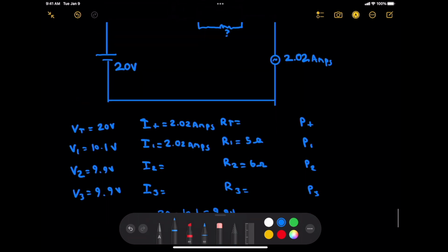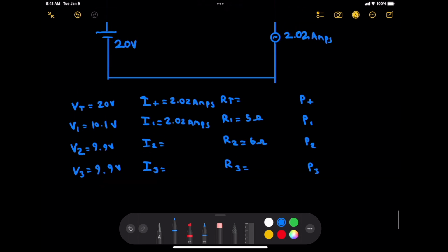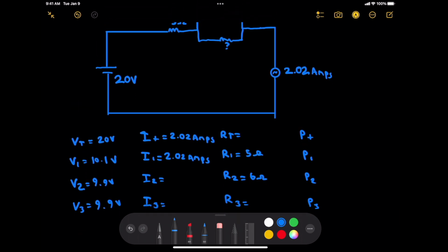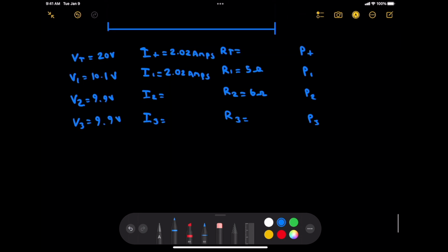And I'm starting to figure out that this is getting a little bit easier as we go along. And sometimes that's the problem. You just need to work what you know, and then what you don't know will come naturally. So, what do we have? We have V2 and we have R2. And it gets its own voltage because it's in parallel, so we can treat it as such. V divided by R equals I, as the triangle shows.